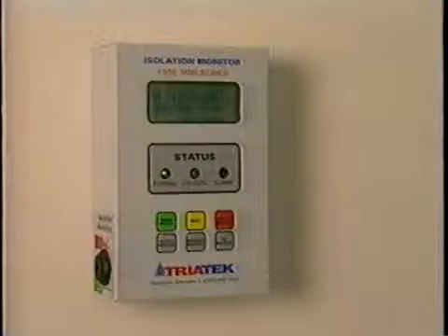A room pressure monitor is an electronic device that continually measures the pressure across a room boundary. It consists mainly of a sensor installed through the wall and a panel that displays the sensor pressure reading, usually in units of inches of water gauge. The measured pressure is compared to a reference pressure value. The monitor is usually programmed to sound an alarm when the pressure falls below the reference pressure and stays there for a certain length of time. The reason for the time delay is to allow staff time to go in and out of the room without the alarm sounding every time.